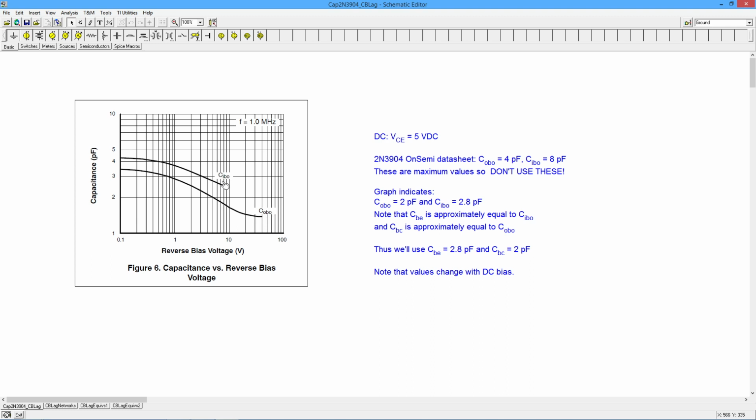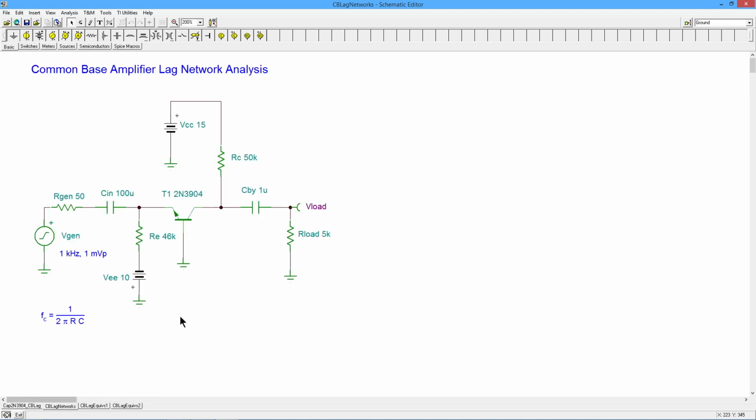So technically, if I go back to this original circuit, imagine this is the measurement circuit. If this is open, then what you're looking at here is an input capacitance with whatever this capacitance is in series with this capacitance, right? Because this is all open, this is all gone.